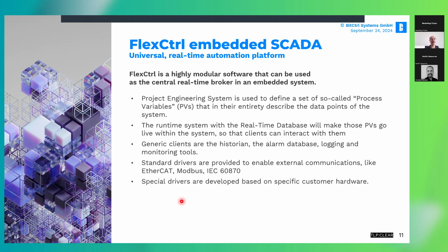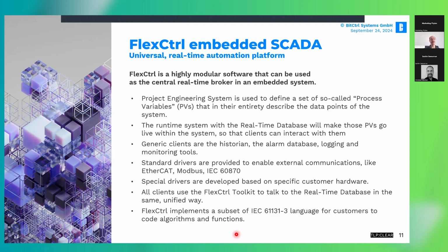And the good thing is that specialized drivers can also be developed, even for specific customer hardware, that can be plugged in very easily, as I will show on the next slide. All the clients use what we call a Flex Control toolkit to talk to the real-time database in the same unified way. In addition to that, Flex Control implements a subset of IEC 61131 language, and that allows customers to code algorithms and functions.